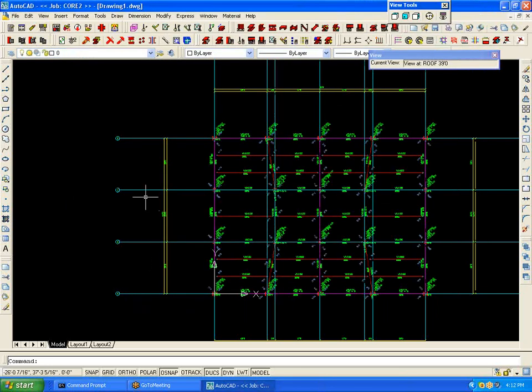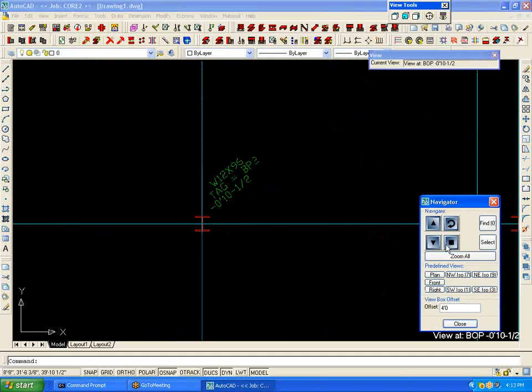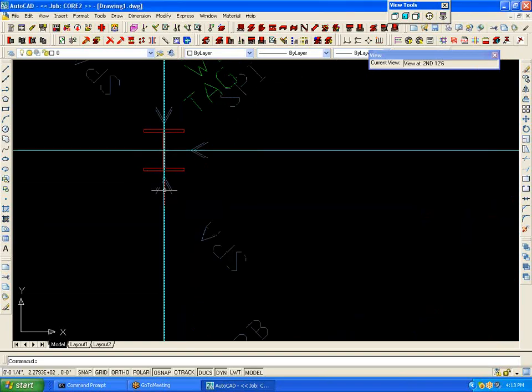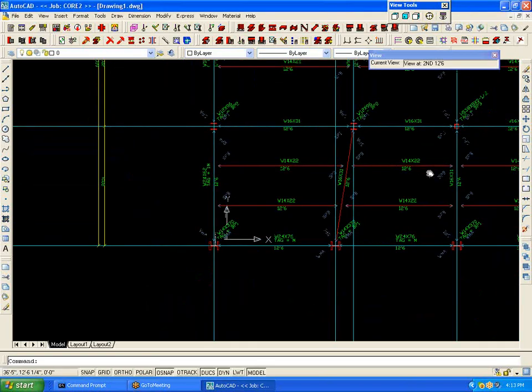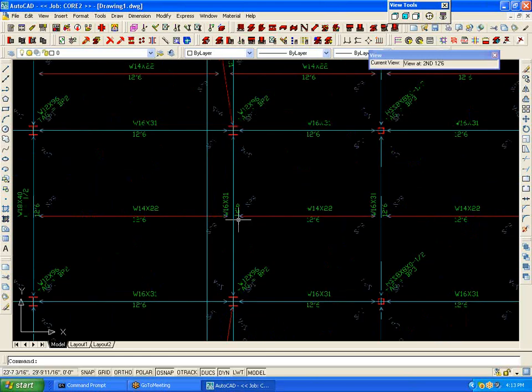It's just a demo. If you look at the model, you'll see the names of the connections. Let's go to a particular floor. It shows you the friendly names. Here's the SPA going to the flange, SPI going to the web. Here's the SPJ through plate connection going to the HSS columns. I did want to do a drag and drop connection, so let's do that. Let's go back to connections.